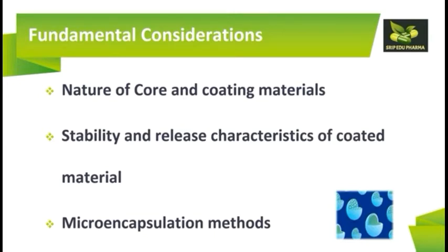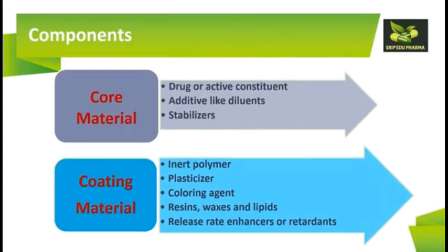So the next difference is in the coating solidification. In spray drying, the coating solidification is effected by rapid evaporation of a solvent in which the coating material is dissolved. In spray congealing, the coating solidification is accomplished by thermal congealing of a molten coating material, or by solidifying a dissolved coating by introducing the coating core material mixture into a non-solvent.